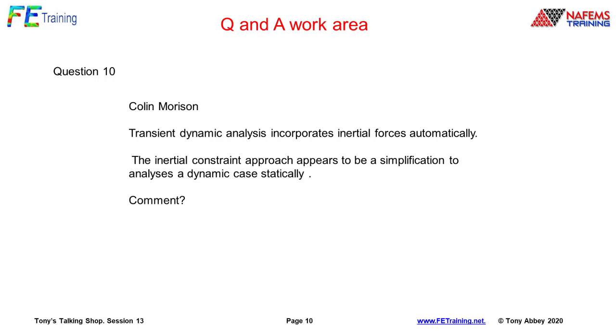Yeah, we could do the same thing in a dynamic analysis, but it would just be a rather expensive way to do it. And also we'd have the problem that any load we apply dynamically just comes in with a bang. So we'd have to ramp the loads up gently. So yes, there would be an analogy to do it in a transient dynamic, but it would be a real pain to do it because we want to get back to a steady state equivalent static condition.